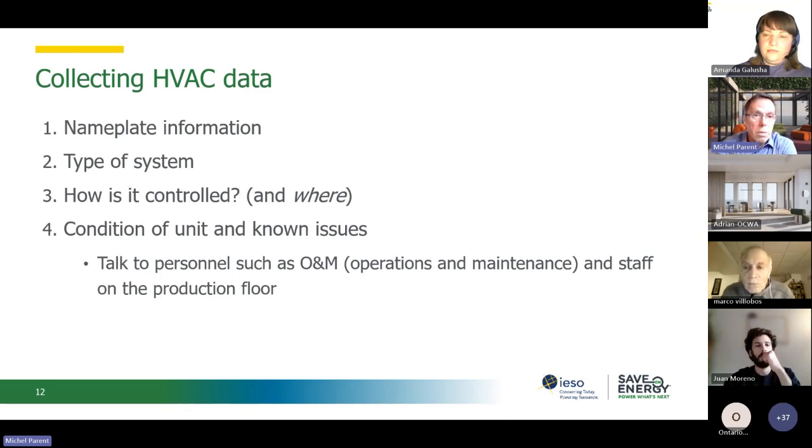A little clue here: a system that has a lot of maintenance issue often hides a lot of opportunity. A pump that always has leaky seal is usually oversized and not working in its proper operating range. So that information is handy to have when you collect the information. And when we go to that third step, you'll see that knowing such things will provide you with possible savings.